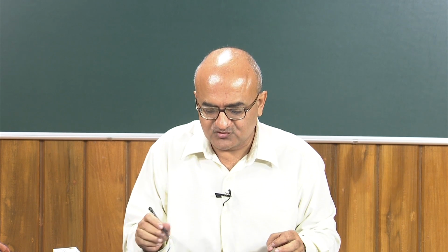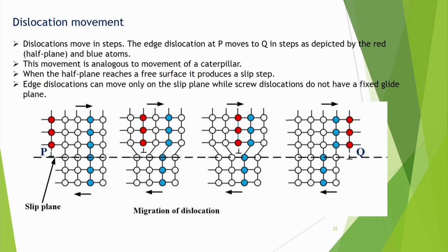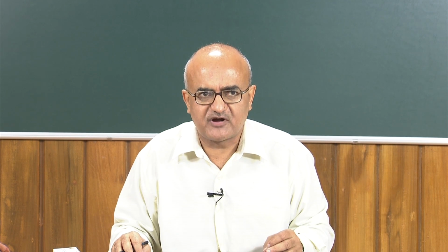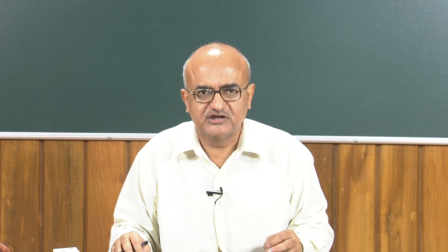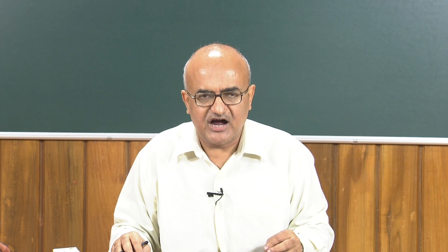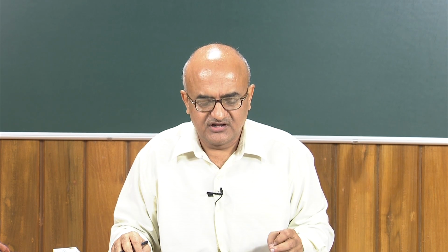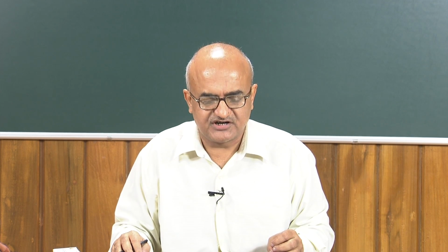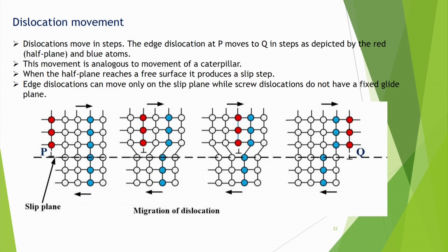But twinning is generally observed in some materials such as hexagonal close-packed materials. Most of the easily machinable materials deform by slip deformation under favorable circumstances, so twinning is not that prominent a phenomenon.